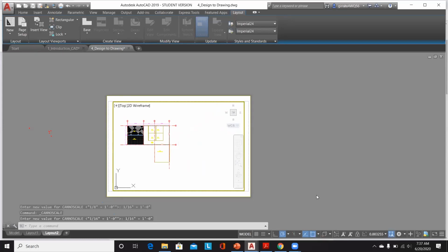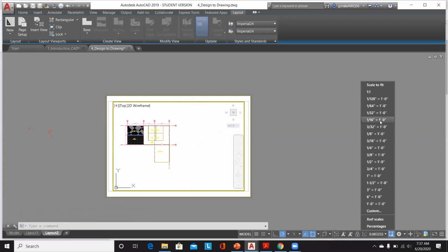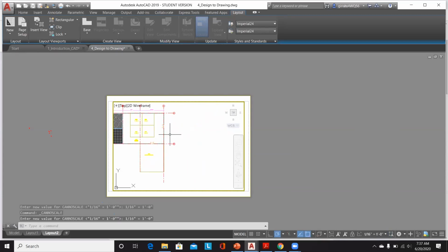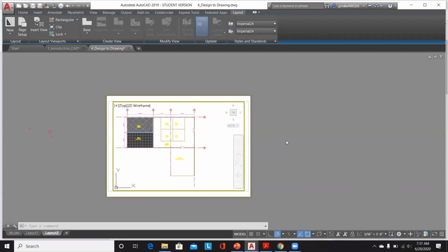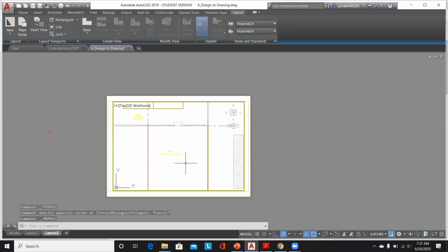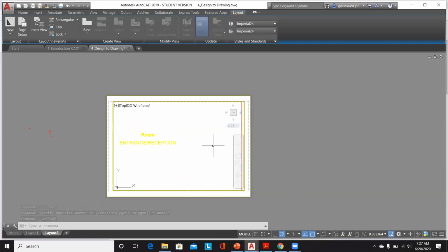So one thing you can pay attention to is, if you set the view scale and adjust your view, you have to use your mouse to adjust the viewport. It will set up, and when you double click out, it will exit out of the model space. When you double click, you can see that the paper space gets converted to model space, and when you scroll your mouse, the scale is automatically changing, which you don't want to happen.